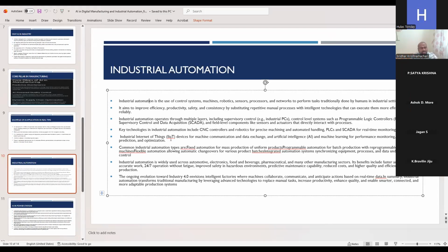Like in AHS also, in the initial design, the normal conventional CFM is achieved by induction motors with the impeller design. Now it is upgraded with DC fans. DC fans are nothing but EC fans, electronically commutated, whereby the AC supply is converted to DC supply, and the same thrust with 30 to 40% better efficiency is attained with EC fans.